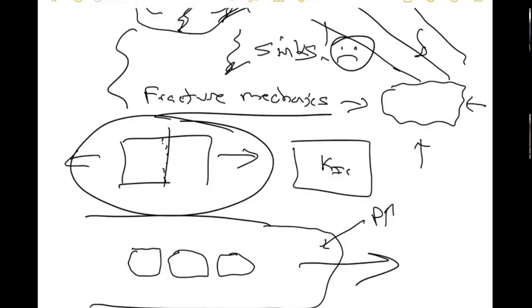That's why your ears pop, right? The pressure outside is lower, so they typically put pressure inside, which means the skin of this material is getting stretched in all directions because it's a tube that's being pressurized. Depending on how these things were fabricated, you would often get small cracks in there, and that massively weakens the structure. Then in a tensile field, under tensile loading, this crack just goes brittle, boom.